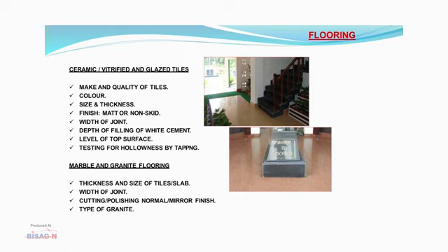The depth of filling of white cement has to be ensured in conformation with the color of the tiles. Also, the level of the surface should be uniform and the sloping towards the drainage plan should be ensured. The testing for hollowness has to be carried out through tapping.